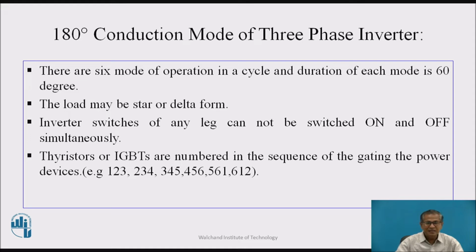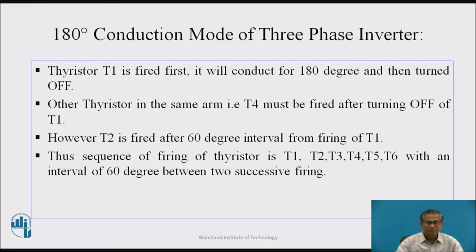Thyristors or IGBTs are numbered in the sequence of gating the power devices. Now, thyristor T1 is fired first.